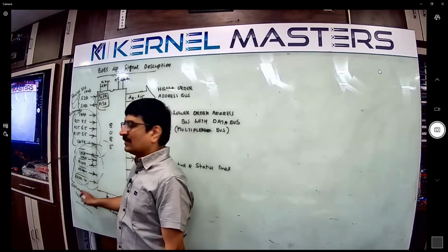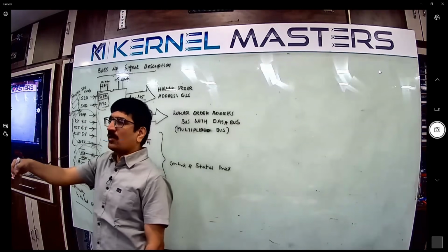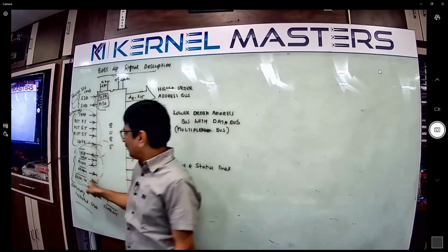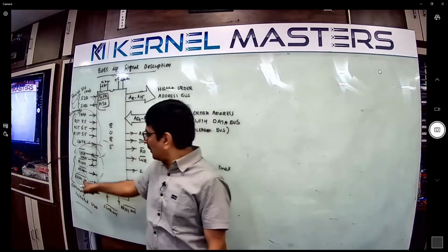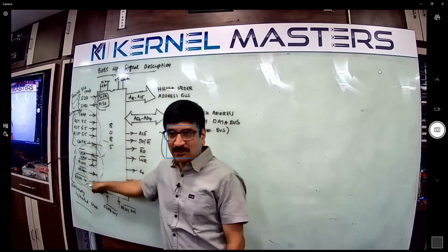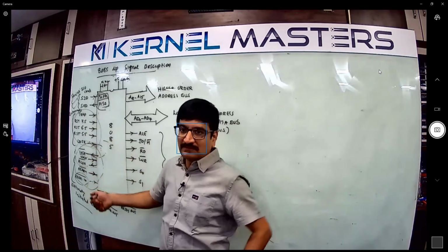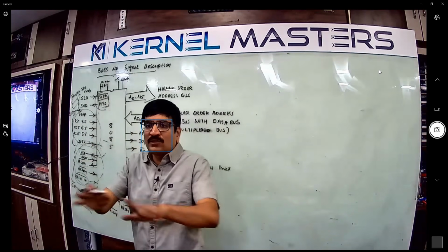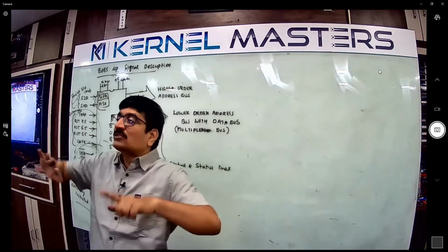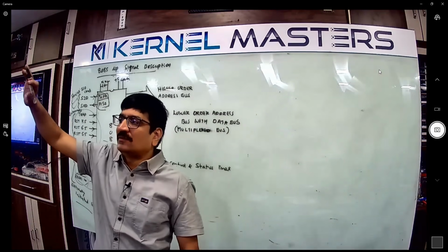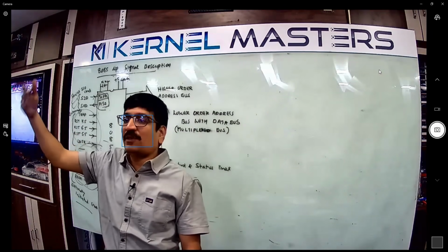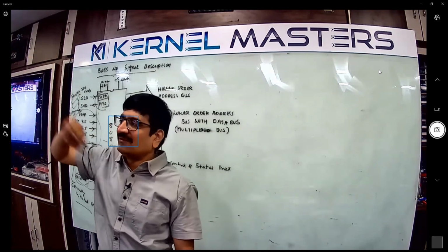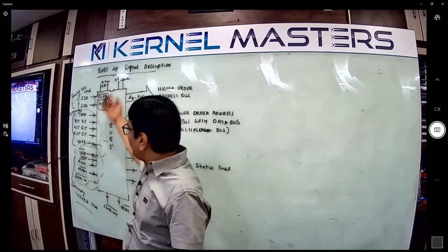Reset In bar. Every hardware board has a reset button, connected here. Whenever you press the reset button, it is also an interrupt, and reset is a high priority. Whenever the reset interrupt occurs, the entire content of the microprocessor goes to 00. You go to the starting of the program, the beginning of your system. The program counter holds the starting program address. Understand? So at the starting moment, it is Reset In bar.